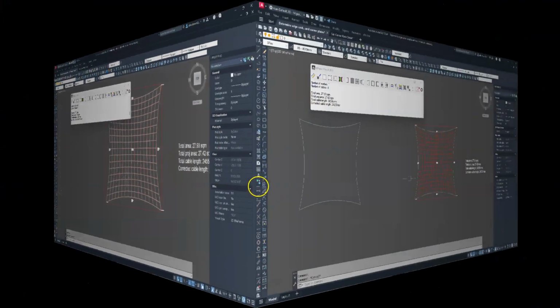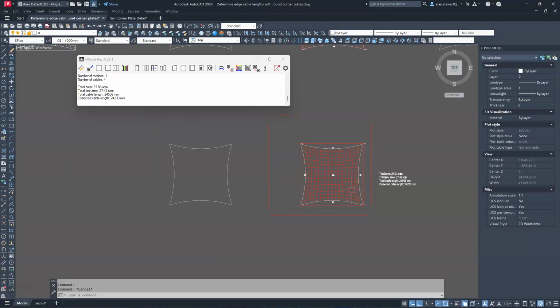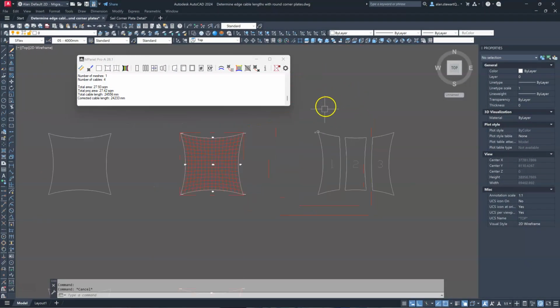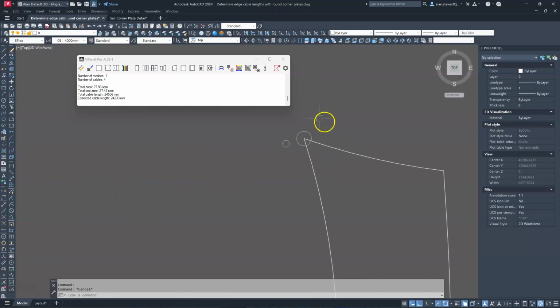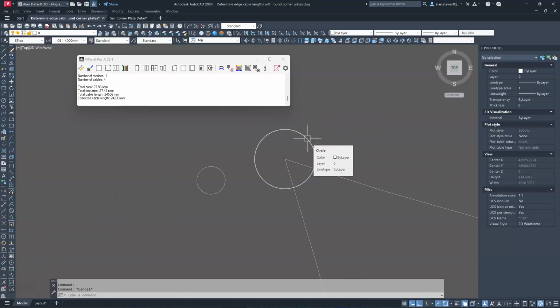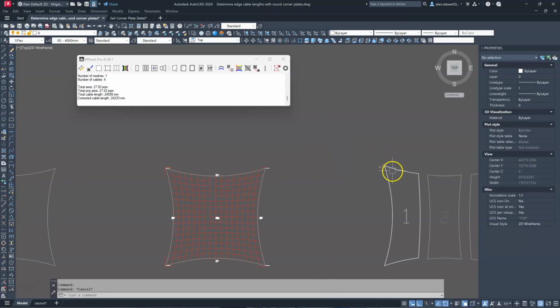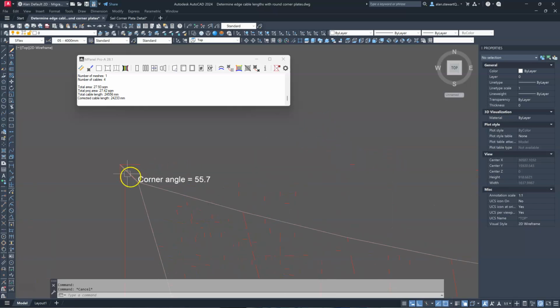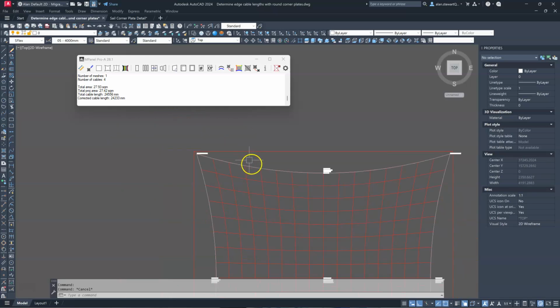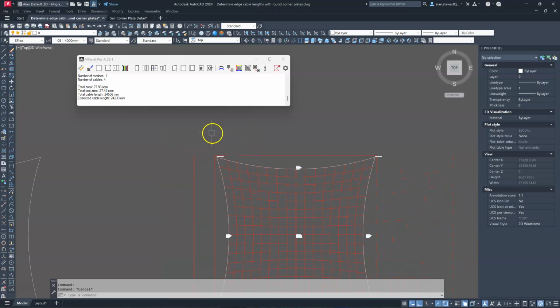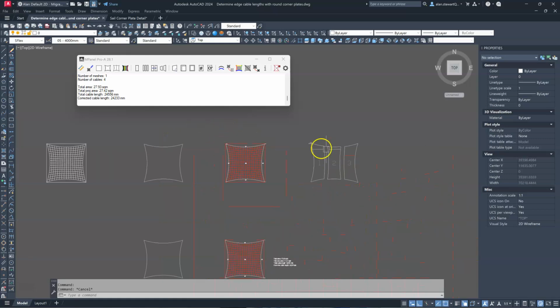Now coming back to the link offset, just to explain this a little further, the original link length was 200mm, and we have a link in this model here of 93mm. Subtracting 93 from 200 gives us 107, which was the link offset number we saw in the extended data.